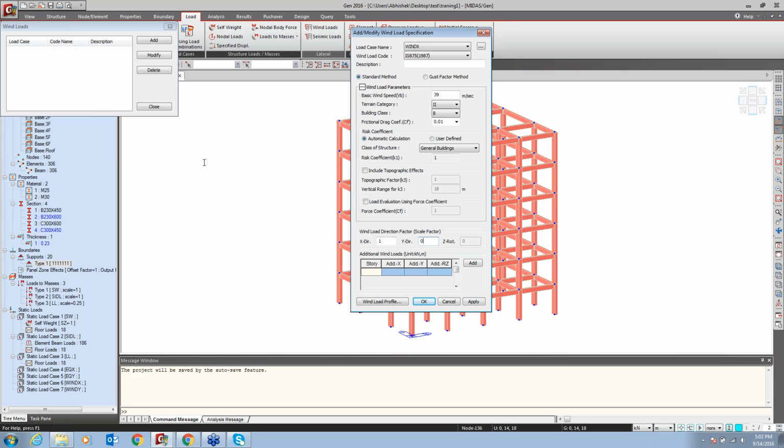Then you have to consider semi-rigid diaphragm, because over there that slab is taking some stiffness. So for that reason we have to consider the semi-rigid diaphragm, and over there each and every node deforms individually. So for that reason no need to consider the rigid diaphragm because of semi-rigid.